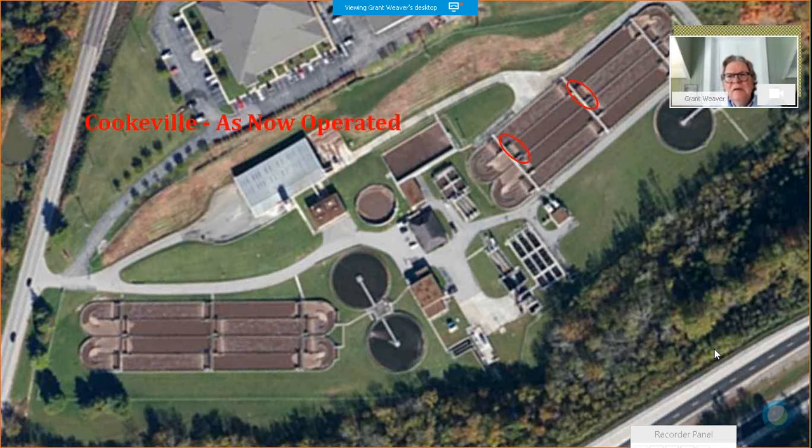Okay. So for phosphorus removal, there's a belief, and I'm a supporter of this belief, that downstream of the zone where the 2 rotors are running, they're getting some deposition. So there's a lower level of wastewater that's getting septic enough to create the volatile fatty acids.